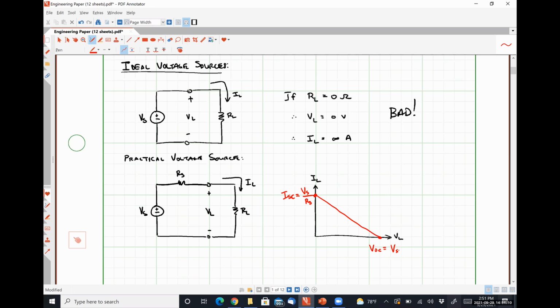My work outside of here, as I've mentioned a couple of times, is for Sabre Building Systems by Selections, where I make very, very large scale battery energy storage enclosures. I test those for short circuit fault conditions by literally using the open circuit voltage and the measured internal resistance of the battery, and then do all of my simulations based on those characteristics.